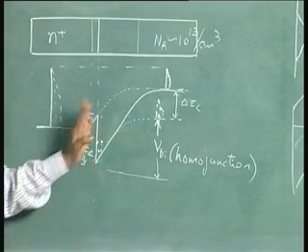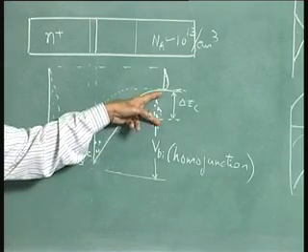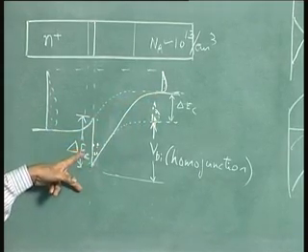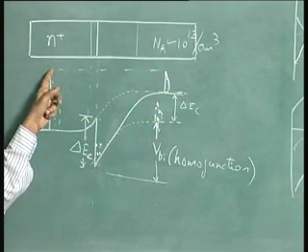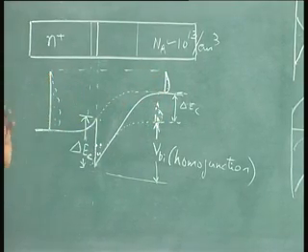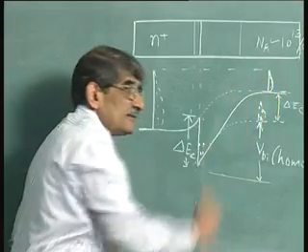So, what you are telling is in the case of a heterojunction, there will be enough electron concentration here because of extra band bending corresponding to this, and the extra band bending is necessary to bring in the thermal equilibrium situation. This is very important to understand: there is an additional delta Ec.